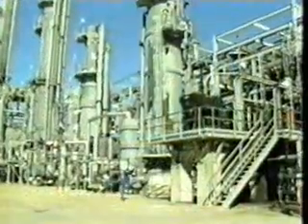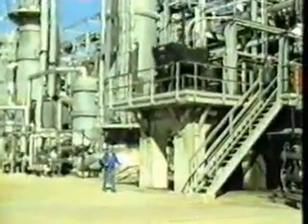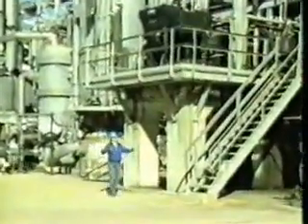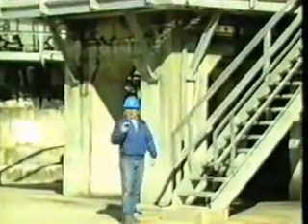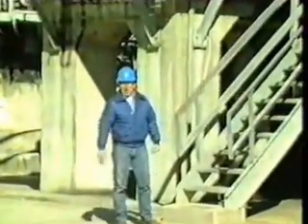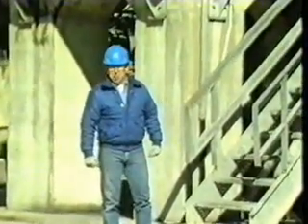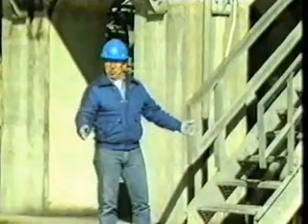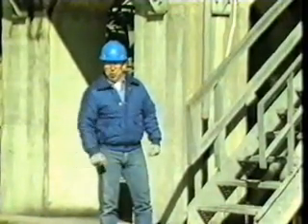When gas and oil are produced together, the gas pressure after separation is often too low to meet the processing requirements of a large plant like this one. Gas pressure also needs to be at levels high enough for proper handling through pipeline sales facilities, gas lift, and injection purposes. So compressors are used to raise the gas pressure and meet these high pressure requirements.